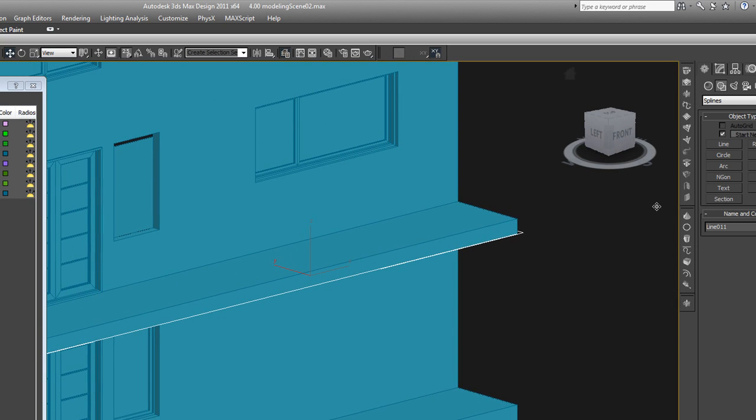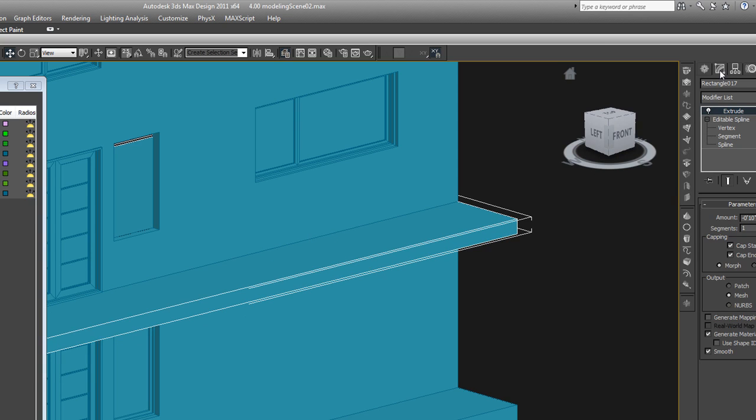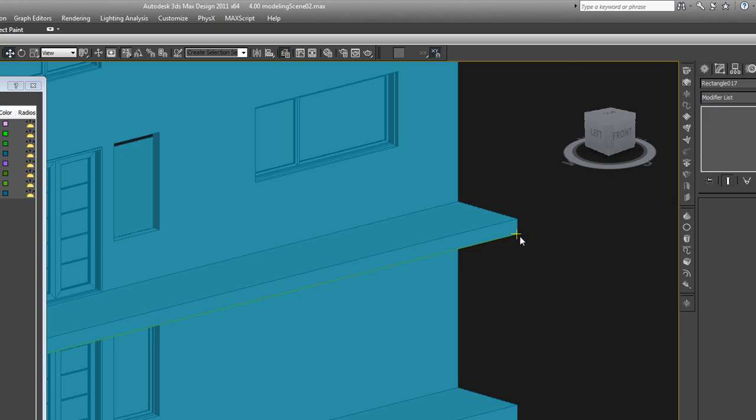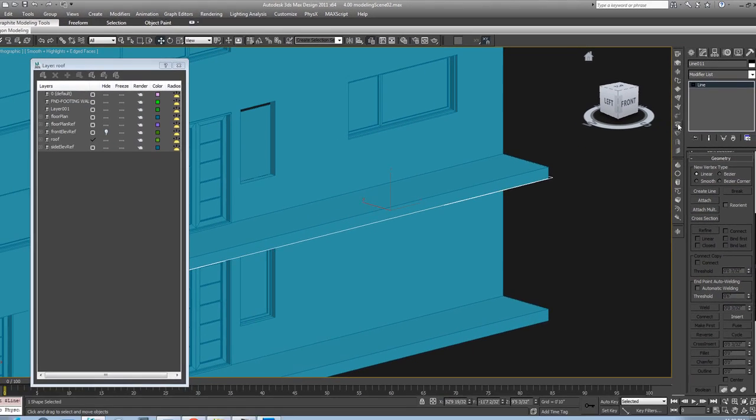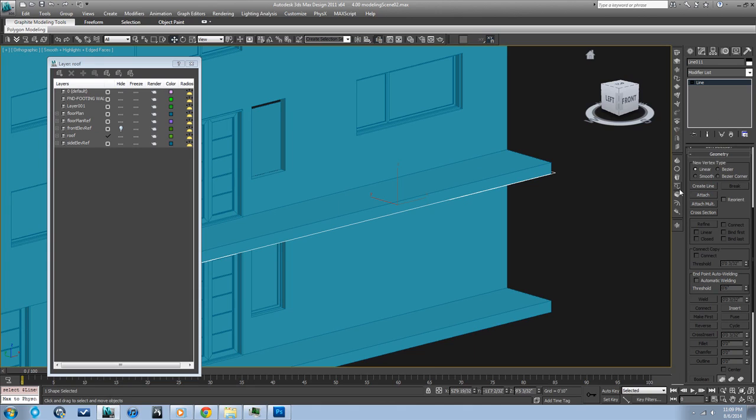And what I will do, an easy way to do it, let's check to see what this is extruded at. That is -10 inches. These railings on the second floor deck like this would be 42 inches above the floor. So that'd be 42 plus the 10 if it's going to be face mounted there. So that would put it at 52 inches.